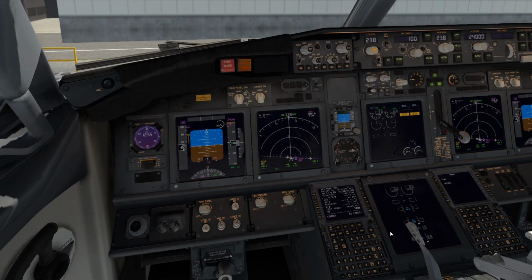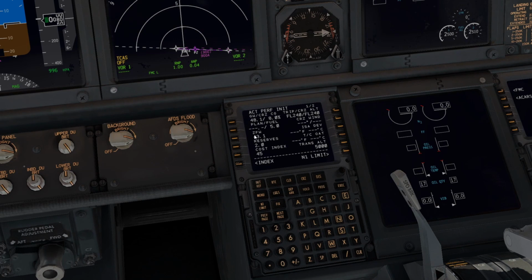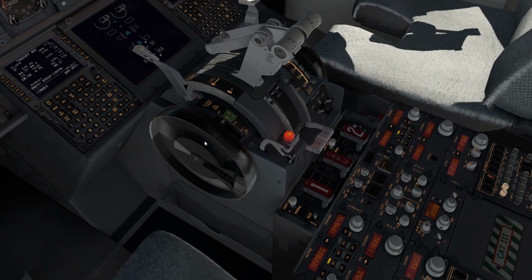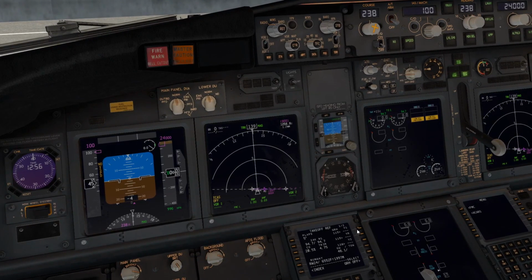Okay, what for us to do, we can continue with the FMC. I'm doing the limits, climb and the takeoff. Flaps we go for 5 degree. We take the center of gravity and we're using the trim. V1, V-rotate, V2, enter the V2, which is 5.